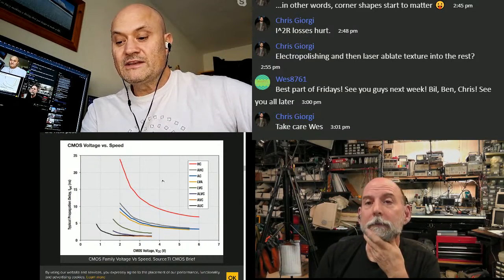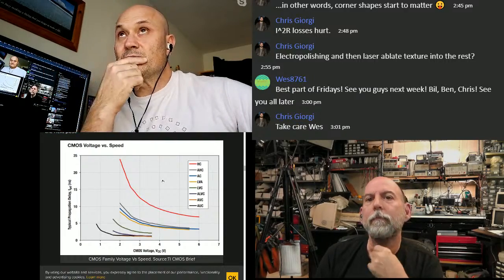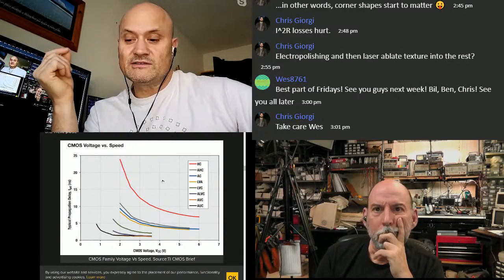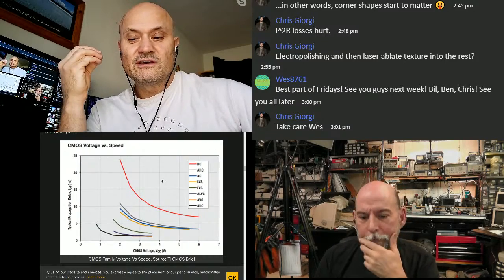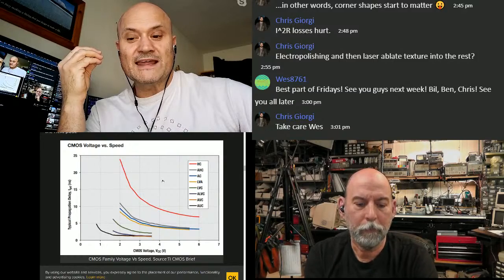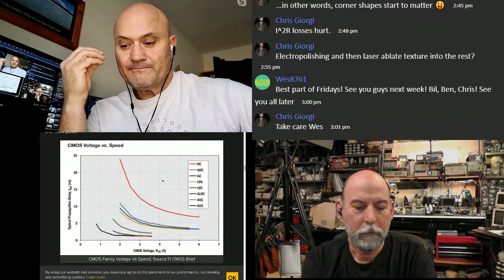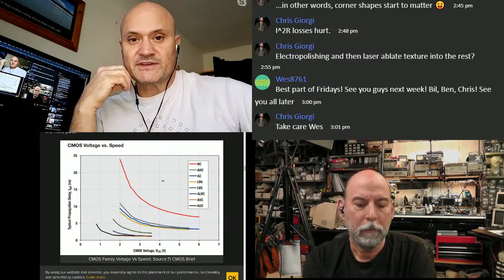Okay. Yeah, and you can request coupons for all sorts of different things. For example, what people normally request, the obvious thing, is if you have impedance controlled traces and you want to measure them with an actual TDR to see how closely the fabricator matched your specification.